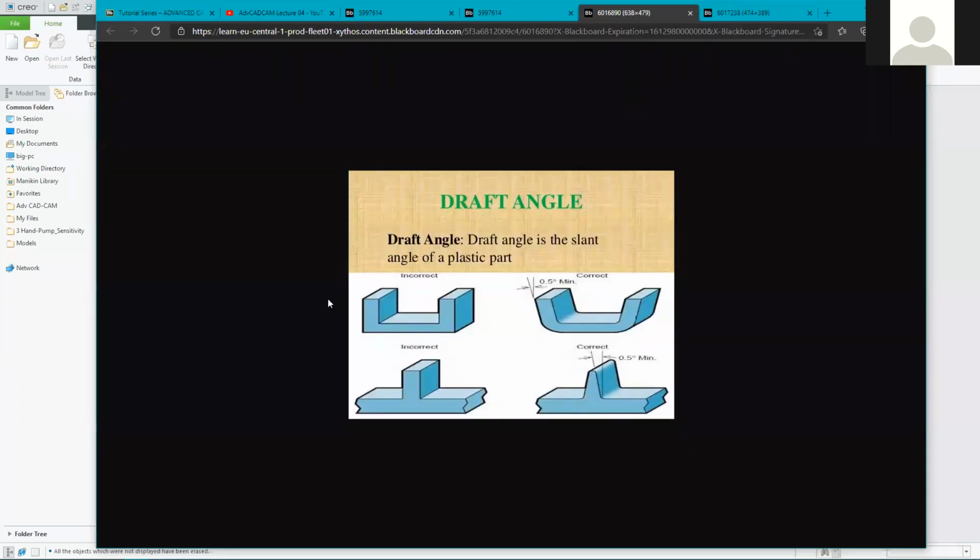So here's a little example. If you were creating a mold such as this to mold something in, when the material that you poured into the mold or injected into the mold solidified, it would be somewhat hard to remove. And that's because these vertical edges remain the same distance apart all the way out of the mouth of the mold.